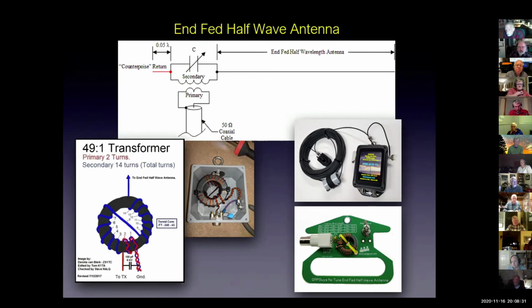Or there's off-the-shelf commercial ones. They're basically a transformer as opposed to a balun, because of the nature of it. There are off-the-shelf ones that are very good, and actually multi-band, because they work on harmonic-related bands, depending upon the length of the half wave that you put up.